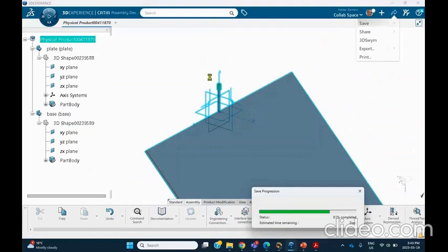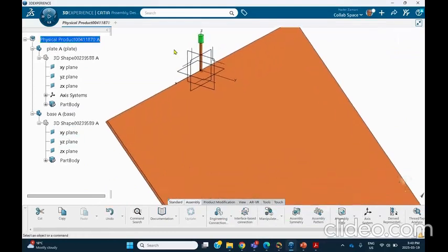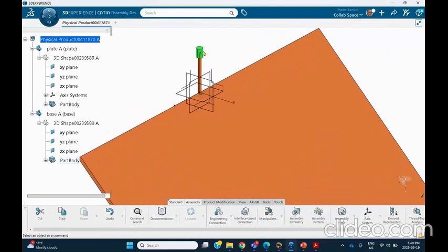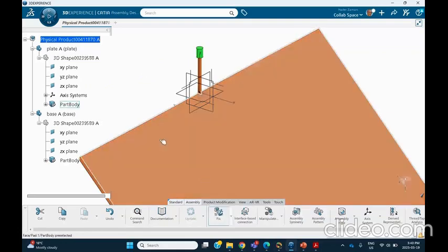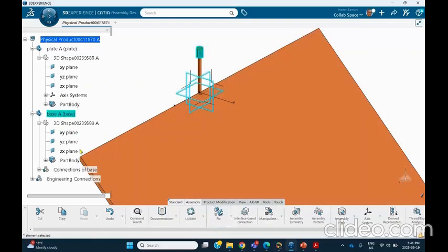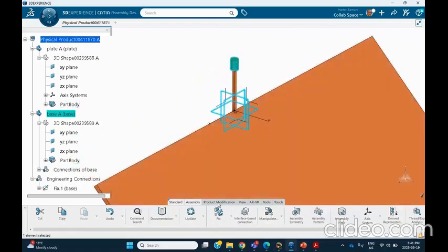Now, we're going to create our joints. So obviously that green one is going to be the fixed part. So let me go ahead here with fixed, and it's the green one. The base is going to be fixed. Yeah, it's right here. Green one, base is fixed. And then we create a revolute between this and that. So we create a revolute.